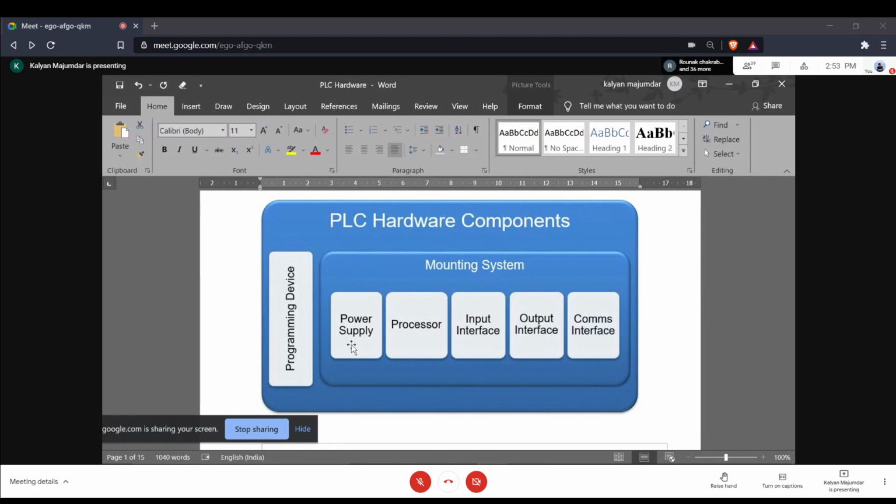The third requirement is that you could have multiple PLCs. In a large plant, you don't have a single PLC controlling the entire plant or all the machines in it. You have multiple PLCs, each controlling a small section of the plant, each controlling one particular machine or probably two machines. And then all these PLCs in turn are connected to a local area network. So how do you connect a PLC to a network? Exactly the way you connect computers to a network.